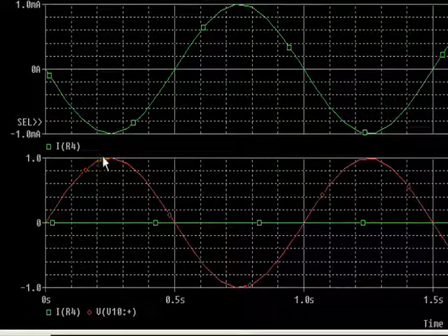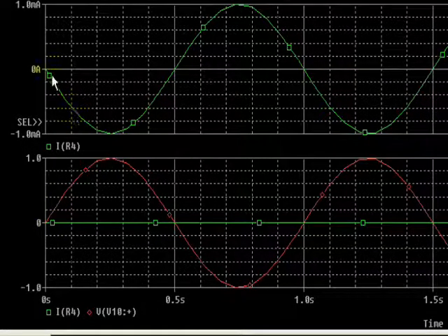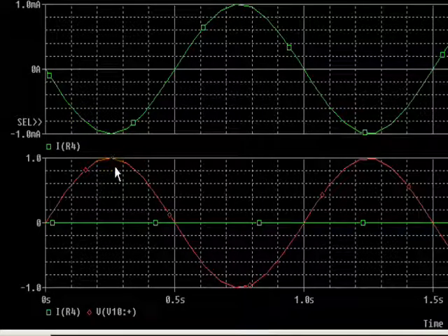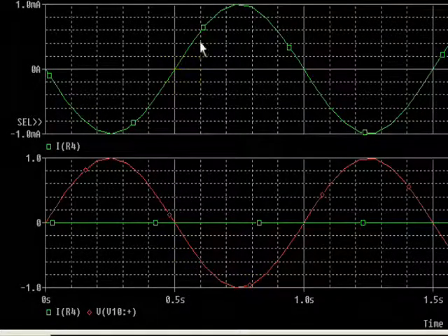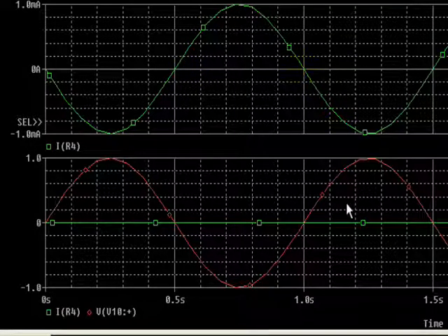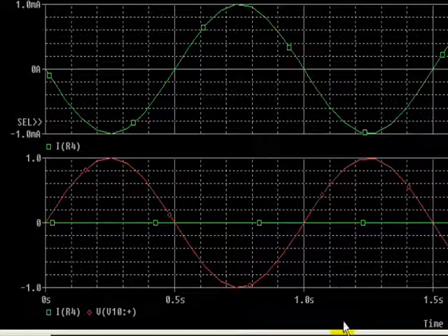As the voltage is ramped up positive, we get a negative current across that resistor, and as the voltage goes into the negative region, we then get a positive current. This shows a reverse relationship, giving us the appearance of a negative resistance.